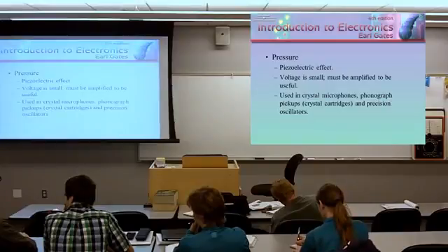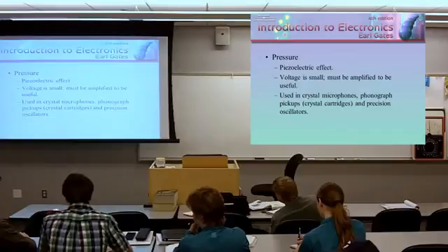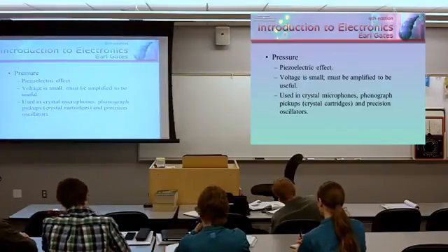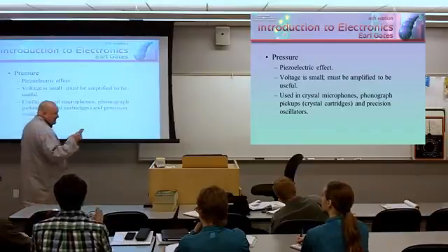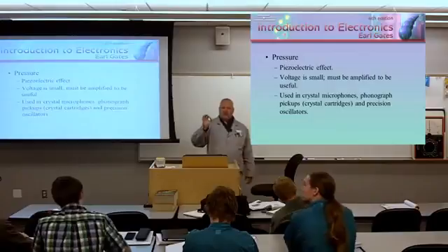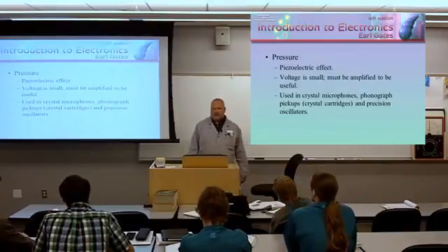Actually, because they're in contact with each other, it will produce... Where would you take the reading at the very end of it? On the tips. Okay. Yeah. So simply by putting the wires together, they are going to be in contact with each other, so you are going to get some reaction, but these thermocouple probes are actually welded. The tips are welded.